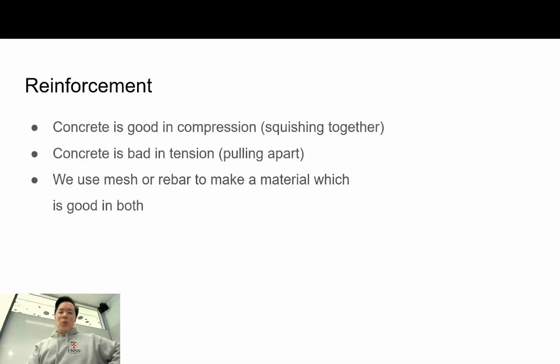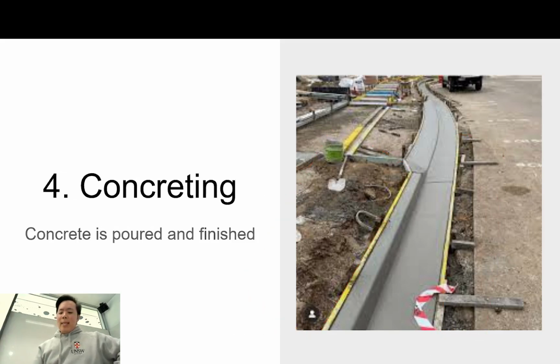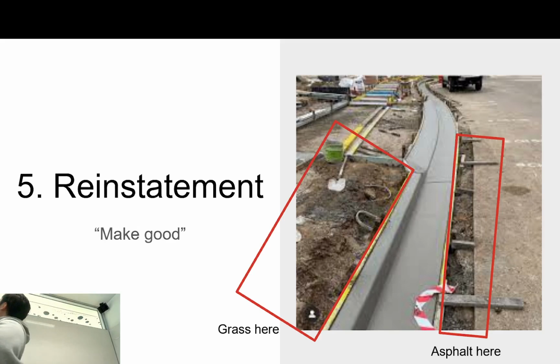So taking that back to our example, when we're pouring this concrete curb here, right, we'll have an agitator come in on the day, and if it's a long bit of concrete there, you might have a boom pump or a line pump, right? And you'll pour the concrete along the whole surface here, right? And you'll have manual labourers come in and shake the concrete. They'll smooth it out, level it, screed it, and then they'll also float the concrete, right? Now, most curbs and gutters that you see don't have a rough surface, as I said. So you just float it and you're done, right? You make sure it's a nice smooth surface and that's it, okay?